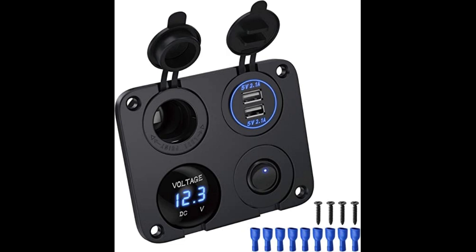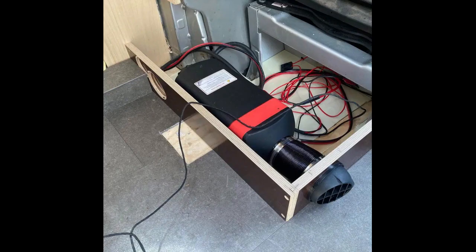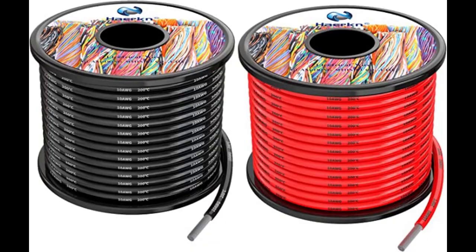So in general, I think the AWG10 5mm squared wire was going to cover most of everything he might need in the rear of his van, even supporting the diesel heater he has there, the electric fan, and the glow plug factor, which I think don't use a whole lot more than 4 or 5 amps initially, and then they drop down to about half an amp. What I've suggested to him is perfect, but it allows for expansion later on, so you could grow from it. It's a good foundation. So I think that's pretty much the DC wiring world covered.